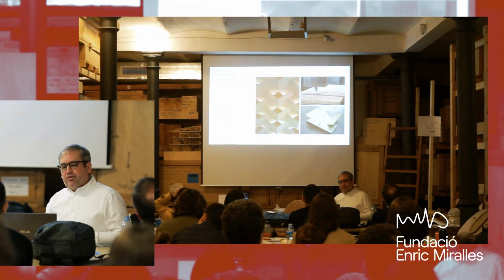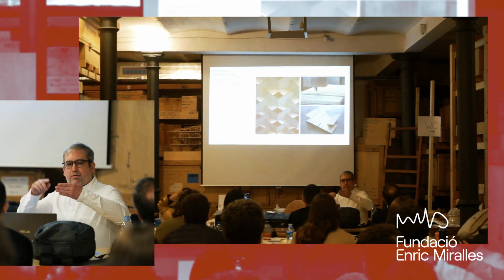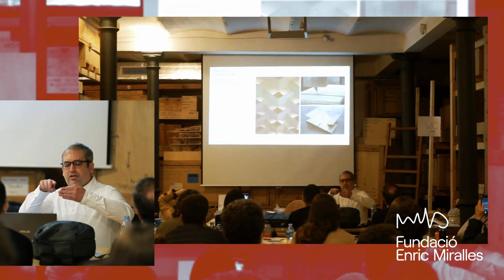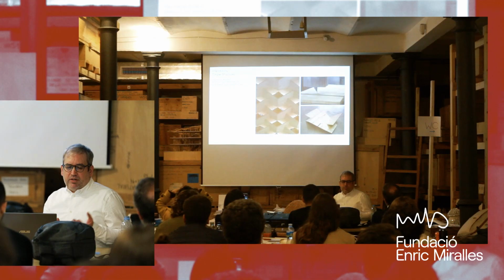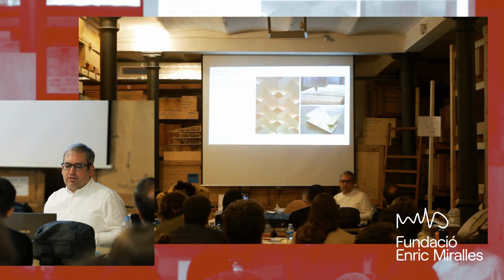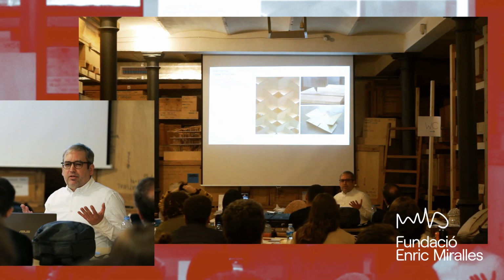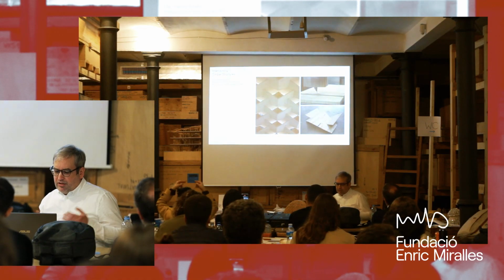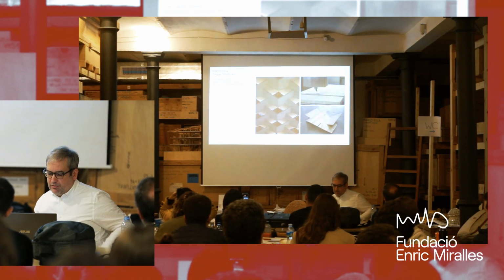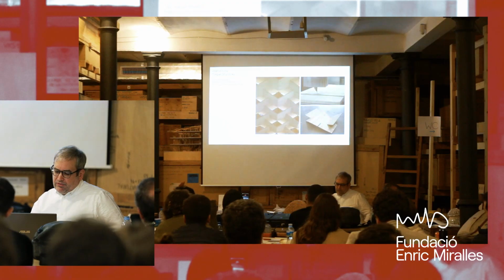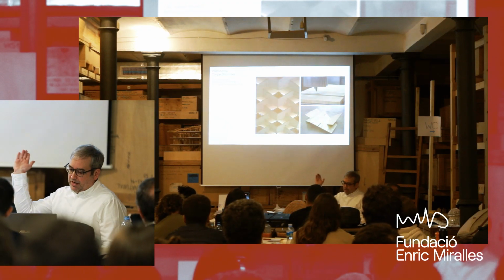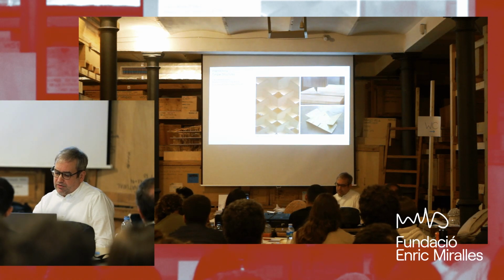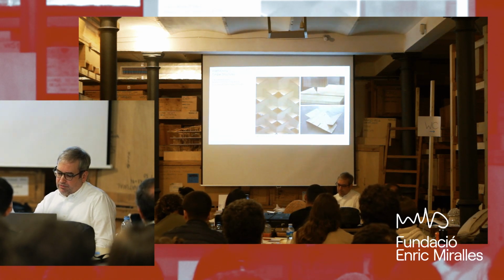So these interlocking structures work with panels that have a slot, and then you slide them together. And this is also, or could be, relevant for disassembly, right? Because it's a relatively simple connection, and potentially it could be taken apart again, and the elements could be used again. So what we have here is a modular structure, and these cuts that you can see here are angled. So you cannot cut it with a normal tool, so you need to have a 5-axis mill.